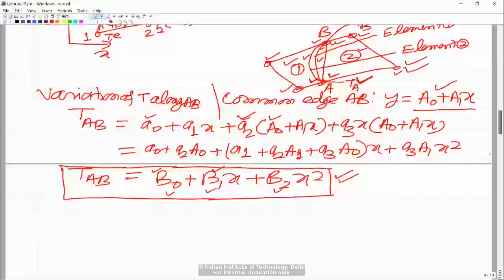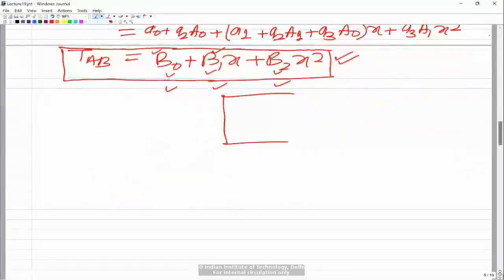Yes, sir. So basically, sir, when you are talking about AB being parallel to one of the edges, then we are talking in the local coordinate system. Yeah, it can be actually in global also, but for the purpose of writing the shape function, we essentially use the local coordinate system. But when you have a rectangular element, even if it is formulated in the global coordinate system, it is the same. The only requirement is that the edges should be parallel to x and y.